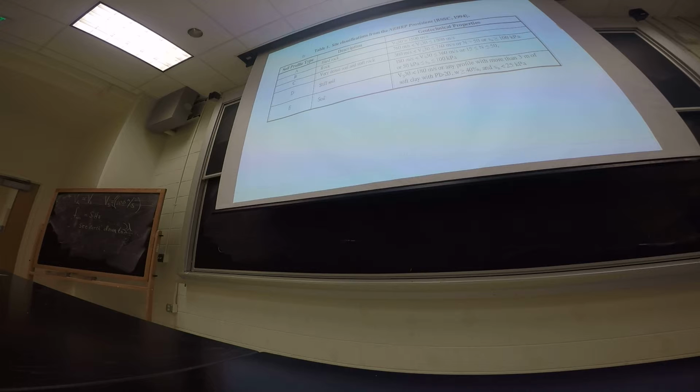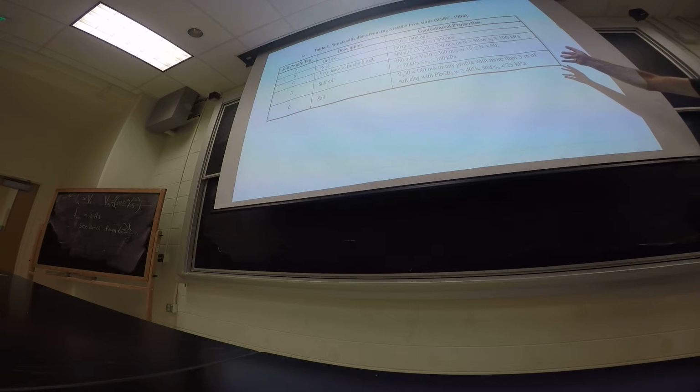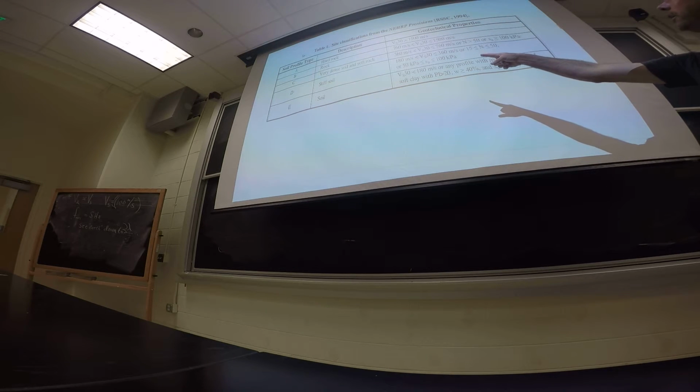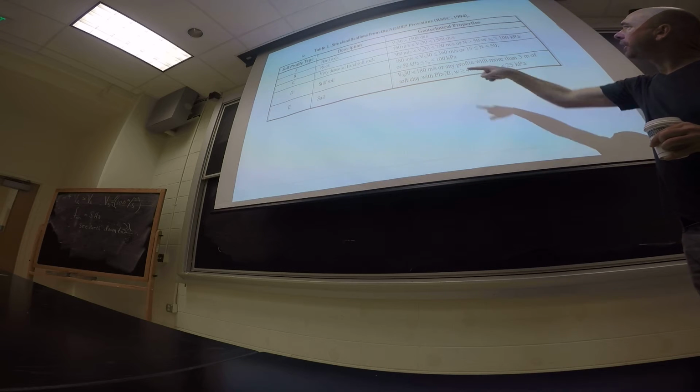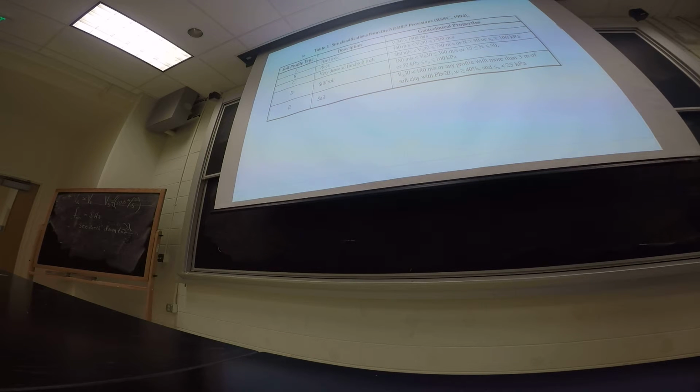Okay, so we use these Rayleigh wave surveys, and we're going to talk about them a little bit. They're called multi-channel array surface wave surveys, MASW. And we use them to characterize geotechnical properties. And the simple classifications for soil are basically soil has this velocity of less than 180 meters per second, or any profile with more than 3 meters of soft clay.